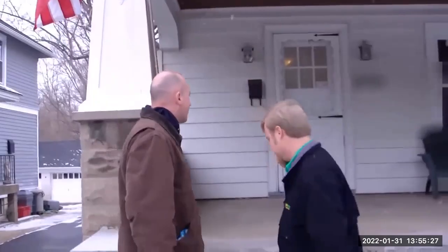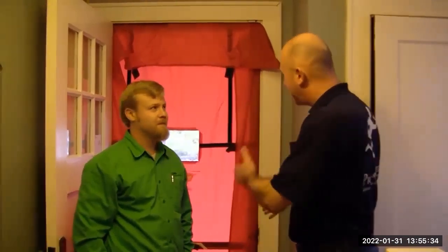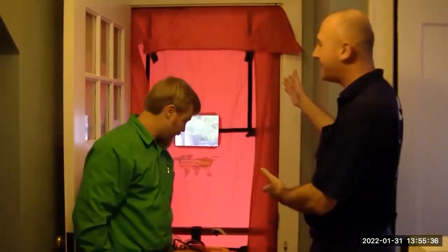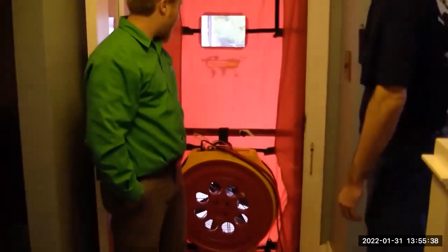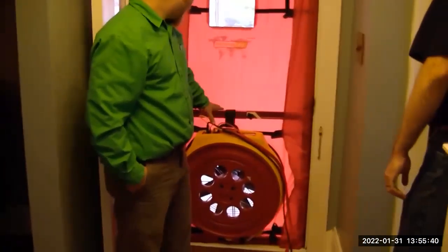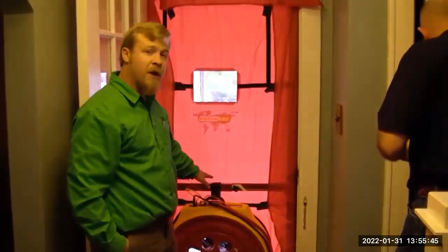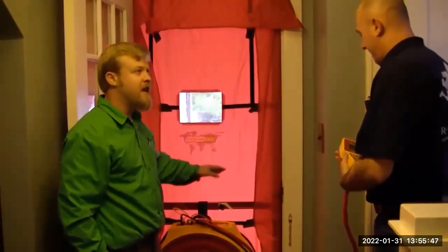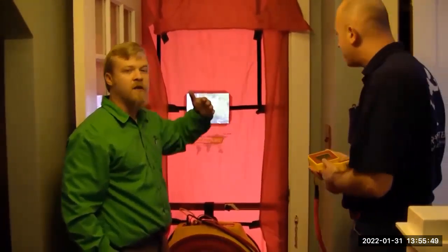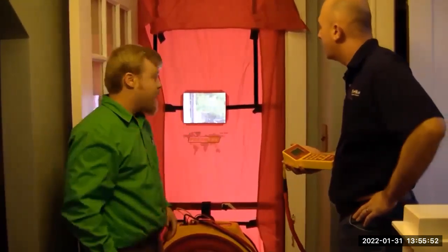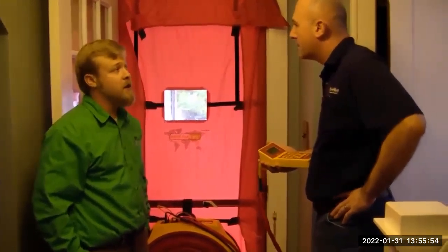All right, we're inside now where it's nice and warm, but I've been watching Tim starting to set up. And the first thing I notice is this large red contraption. What, are we going camping, Tim, or what is this? Well, this is what we call a blower door. What we use this for is it puts the house under a negative pressure. Basically what that means is it's simulating a 10-mile-an-hour wind blowing constantly on our four walls of the home. That way we can see where there's any type of air leakage in the home, be it from the windows, the doors, basically the entire building envelope itself.